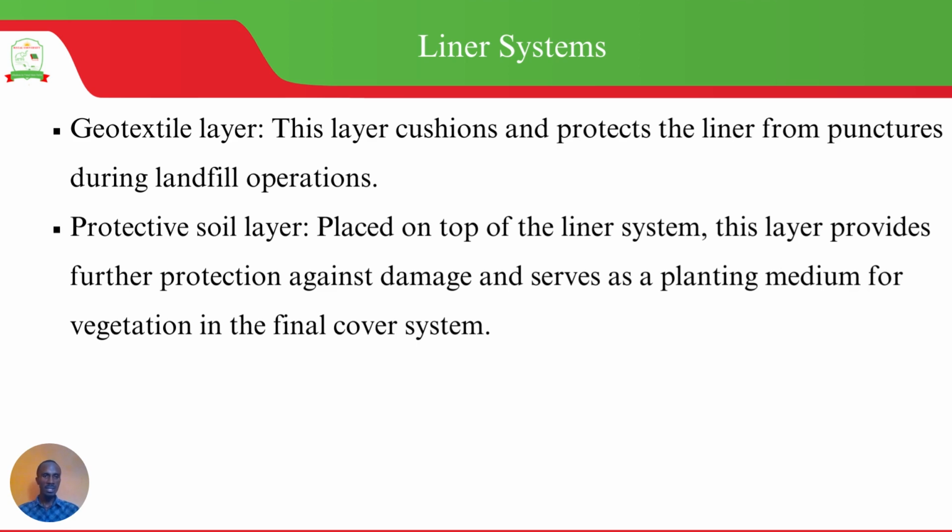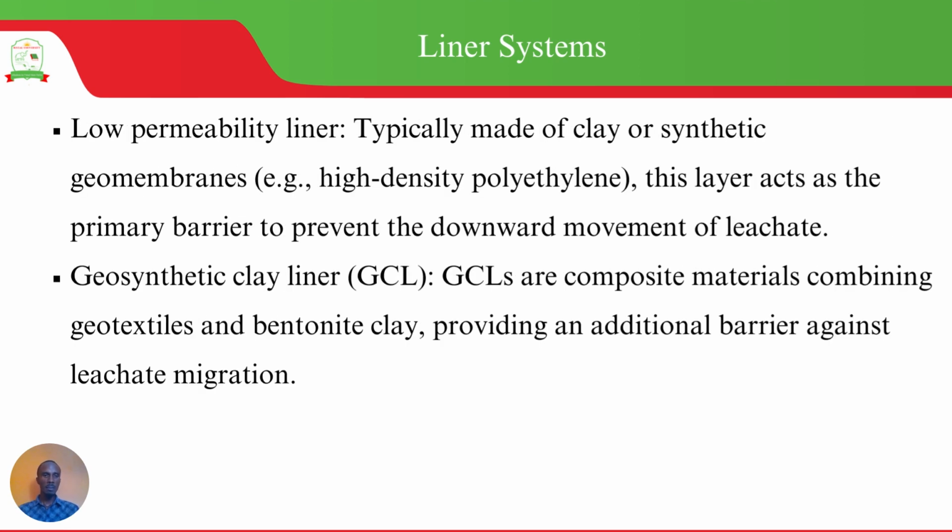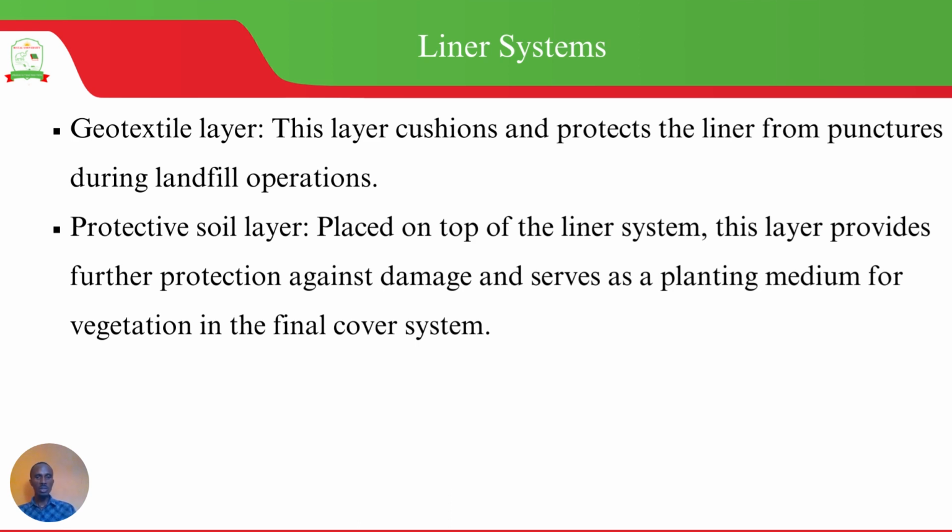Then the geotextile layer protects and cushions the liner from punctures during landfill operations, like turning of that waste in the landfill. You know, those garbage trucks turning around. All that could puncture these liners. So for you to protect them, you use this geotextile layer.